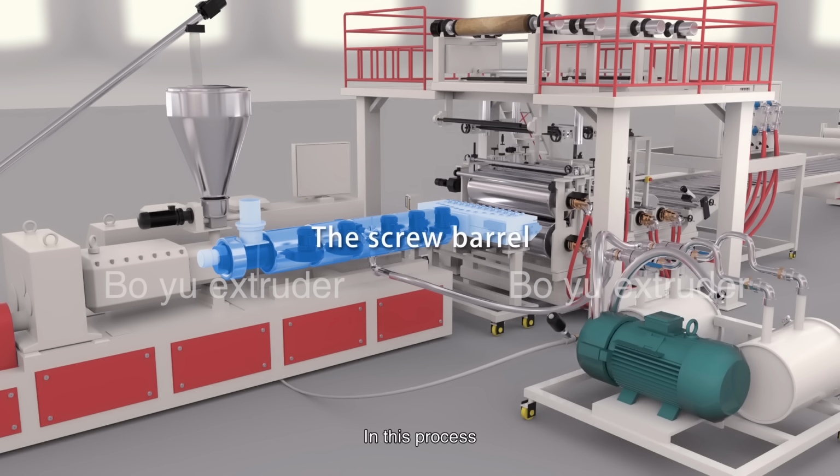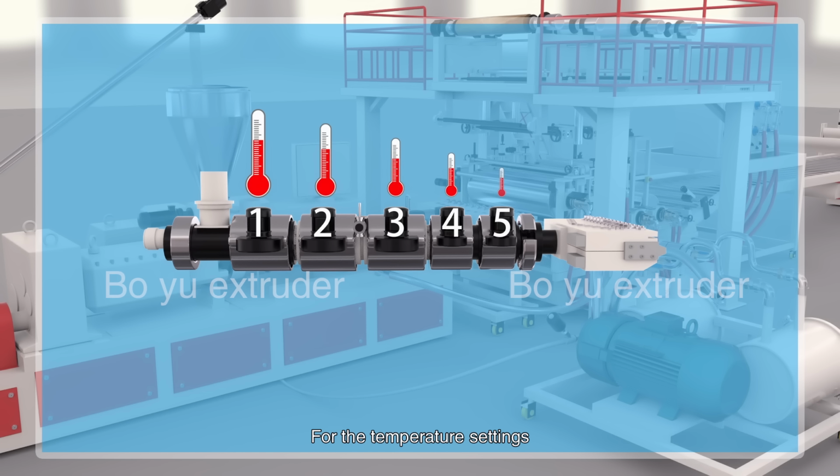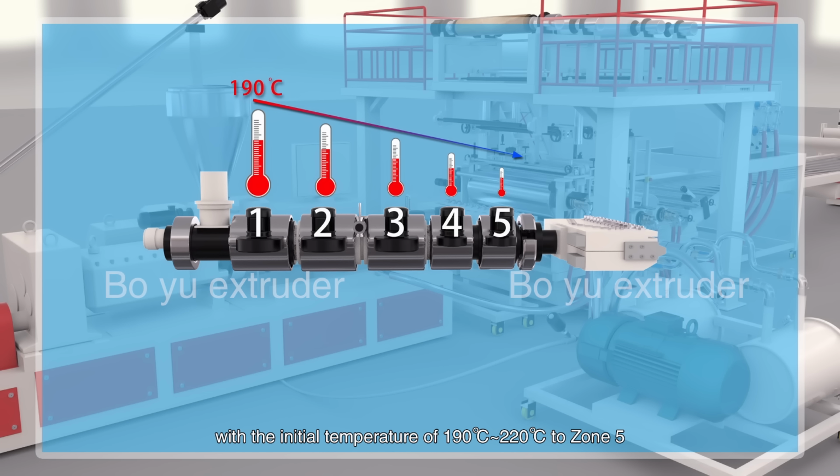In this process, the temperature control is the most critical link. The temperature control of the Boyu SPC Floor Production line is divided into 5 zones. For the temperature settings, it gradually increases from Zone 1 with an initial temperature of 190 degrees centigrade to 220 degrees centigrade in Zone 5.